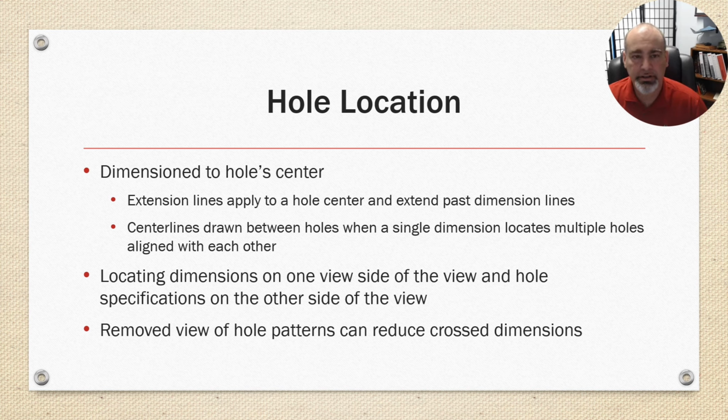So that's where it's very similar to a detail view. It's shown removed. It's labeled with a letter like a detail view, but you don't have a circle circling the primary view, its parent view where it came from. And they often have a scale factor associated with them.